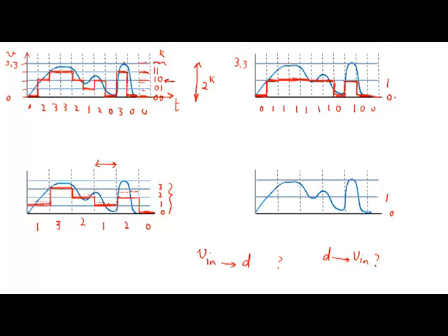So first of all, what is the resolution? Your resolution in terms of volts is going to be your Vmax divided by 2 to the n minus 1, right?